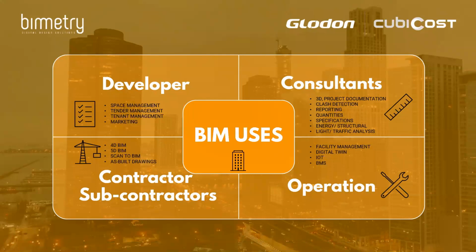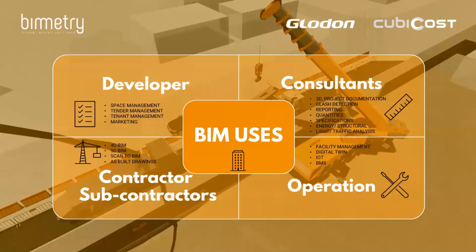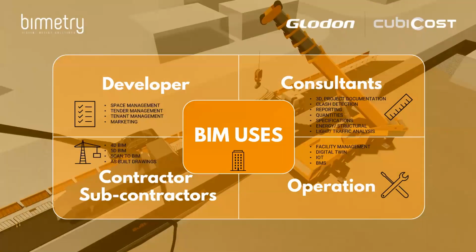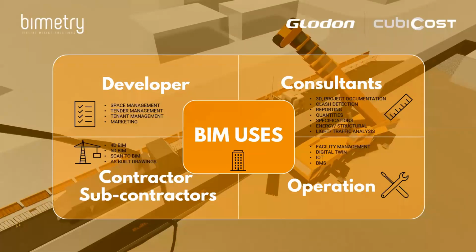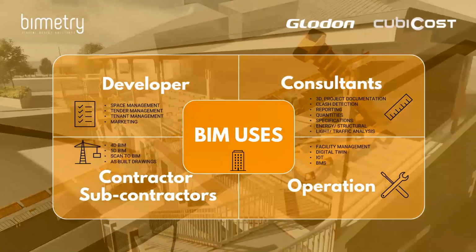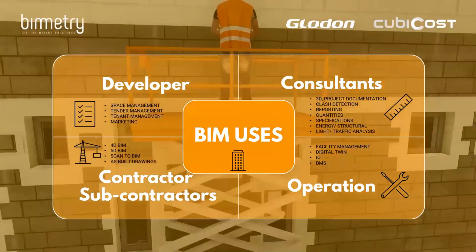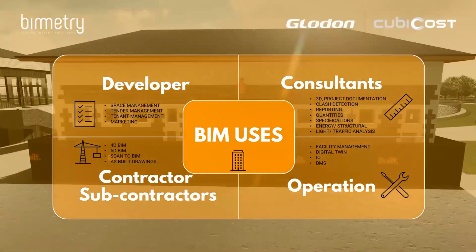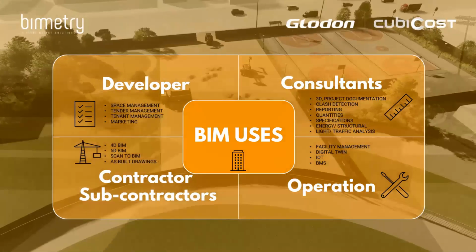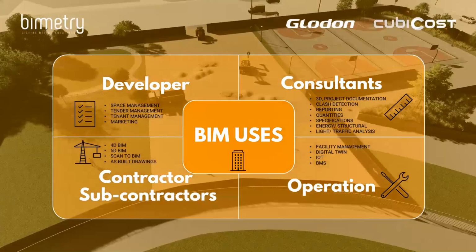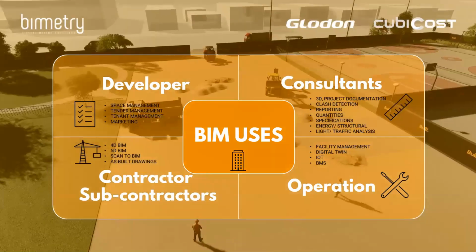The construction companies are also interested in the BIM models, and there are so many tools nowadays that can make their life easier and improve the quality of the construction product. One quite common scenario in which a general contractor might want to have the BIM models is to run a 4D construction animation sequence. 4D sequences are 3D animations linked to the construction program. The sequences help rationalize the construction on site.